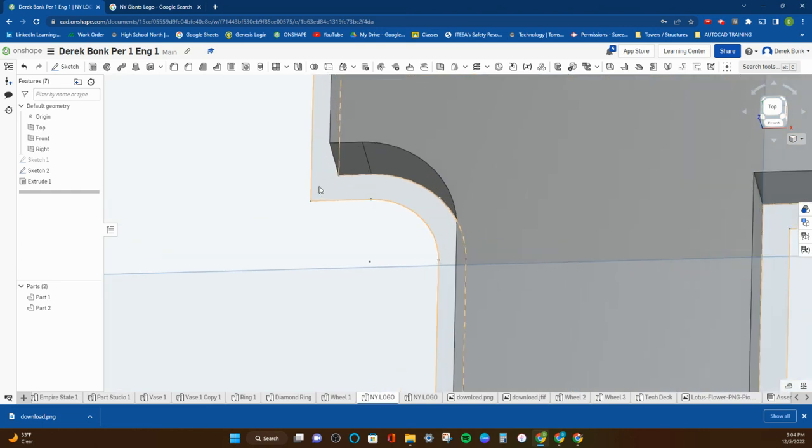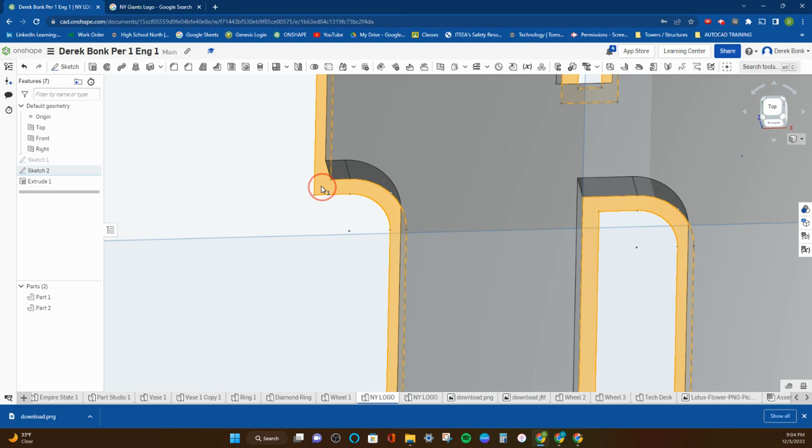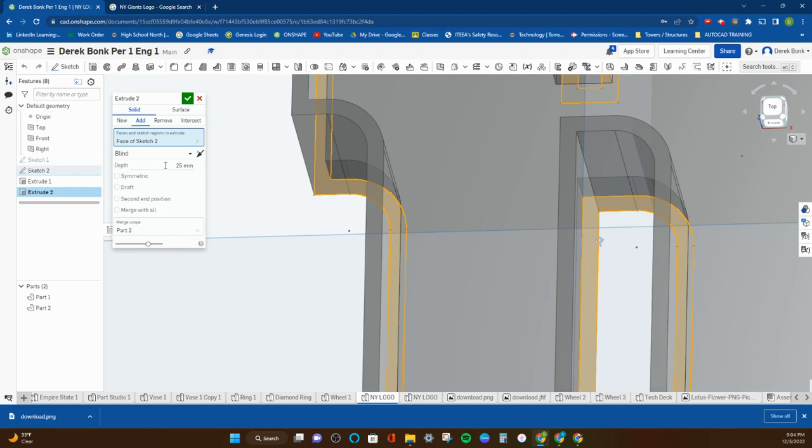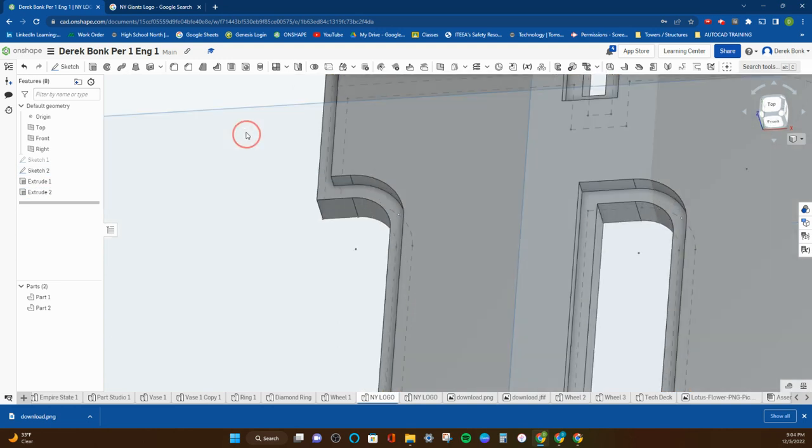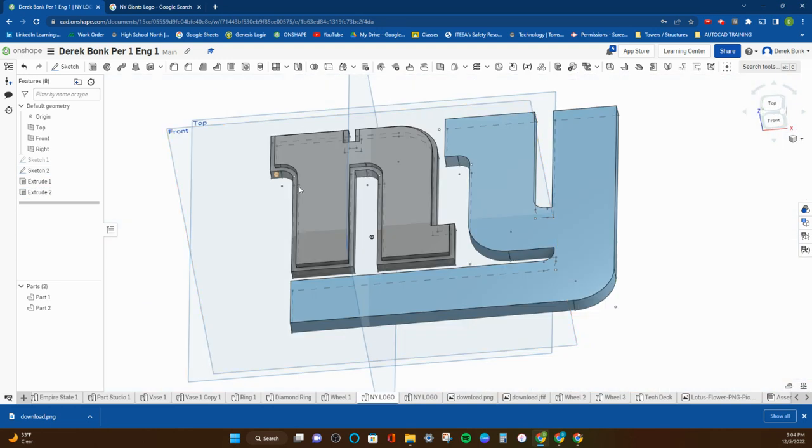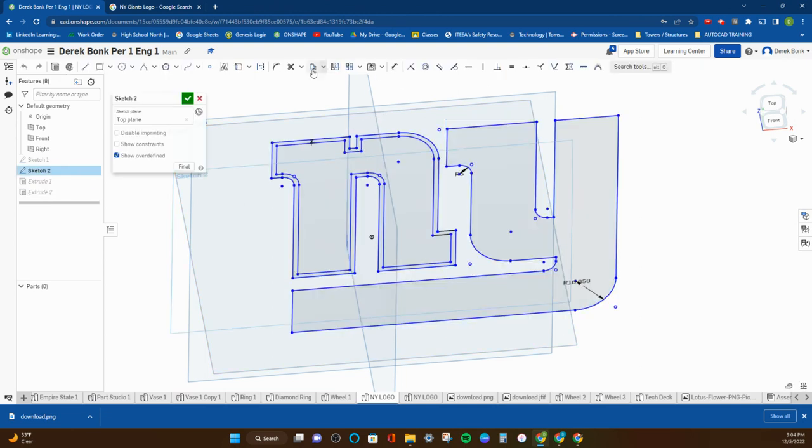Sometimes you do have to zoom in very close and carefully to do something like this, but let's say I just made this 6, I can make this something like 4 now, and I can select that, and click this button, and change this dimension here to 4, hit the check mark, and done. So again, you can see there's certain things that can happen really quickly. Let's see if I can do this super fast for demonstration purposes here.